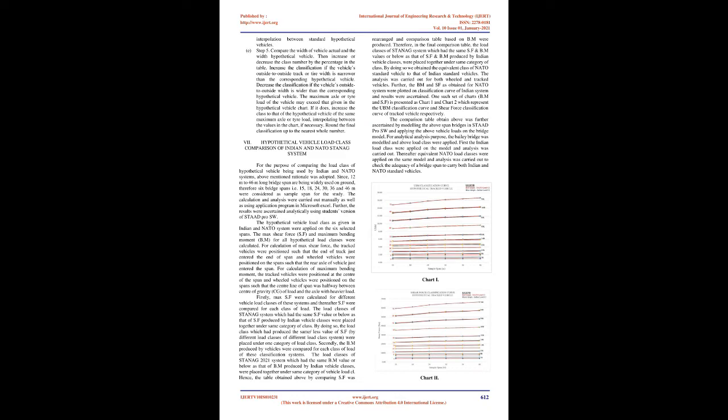A bridge is classified by giving it a number equal to that of the highest standard load class whose effects, UBM, shear, axle load, etc., it can safely withstand for an unlimited number of uses. Thus, vehicles are classified by giving them a number, which is independent of any particular bridge that they may cross. Similarly, bridges are classified or designed for a standard load class and not for any specific vehicle.